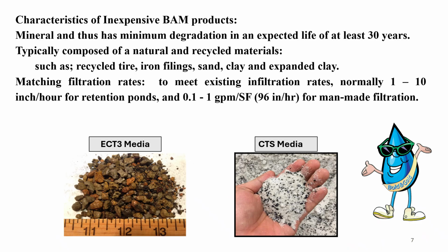When looking at inexpensive, best available media products, there are several important characteristics to understand. Because these media are mineral in composition, they experience minimal degradation over time, giving them an expected service life of at least 30 years. That long lifespan is one of the key advantages of going with a mineral-based approach. These products are typically made from natural and recycled materials, which keeps costs down while still delivering effective treatment.